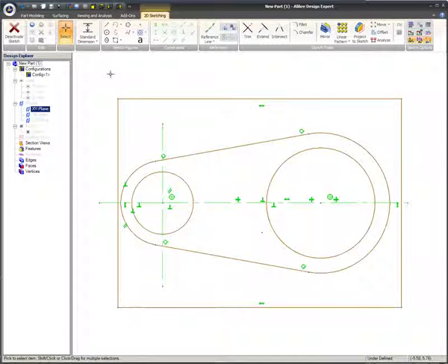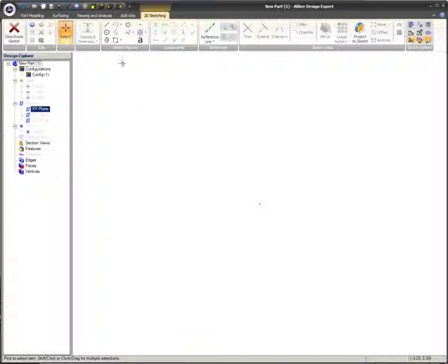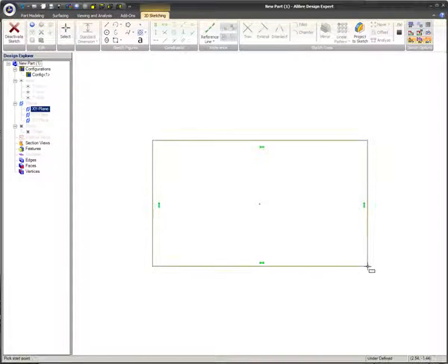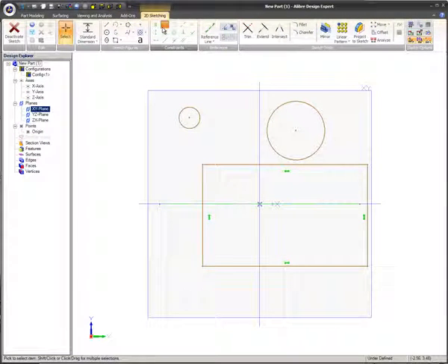Several sketch constraints can be used within the same sketch. When you make a box by sketching 4 lines, the vertical and horizontal constraints get populated automatically. You can also make this box symmetric about the XY axes with the symmetrical constraint.